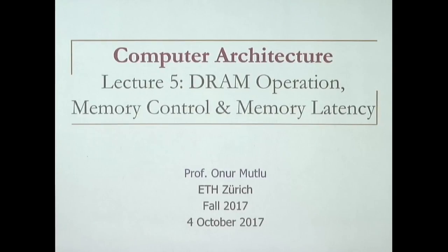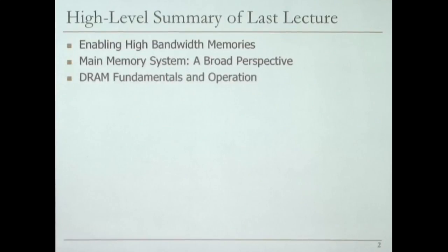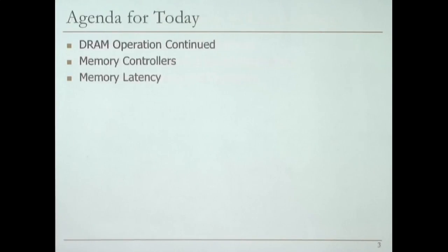So we will cover more of DRAM operation, talk about memory control, and hopefully get to memory latency. Because as you know, latency is not improving as fast as other things. But this is a very quick, high-level summary of last lecture. We talked about enabling high-bandwidth memories. So hopefully you remember that. Main memory system, we gave a broad perspective, and we talked about DRAM fundamentals and operation. Okay? We talked about a lot of trends in the main memory system.